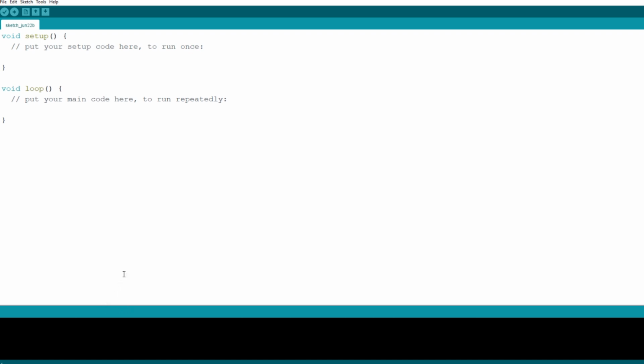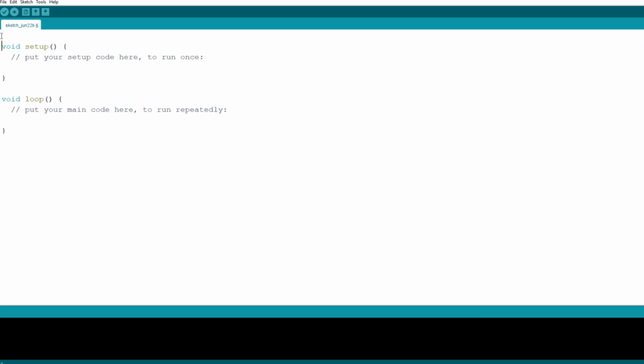And also then we need to add a new library to our source code for servo motor control. The name of this library is Servo.h, so let's include this now. As you know, if we want to add any library to our Arduino code, what we have to do is include our library. So for this operation, first let's use a hashtag here, and write include, and also let's use the less-than and greater-than signs, and inside them let's include our Servo.h library, and we are done.